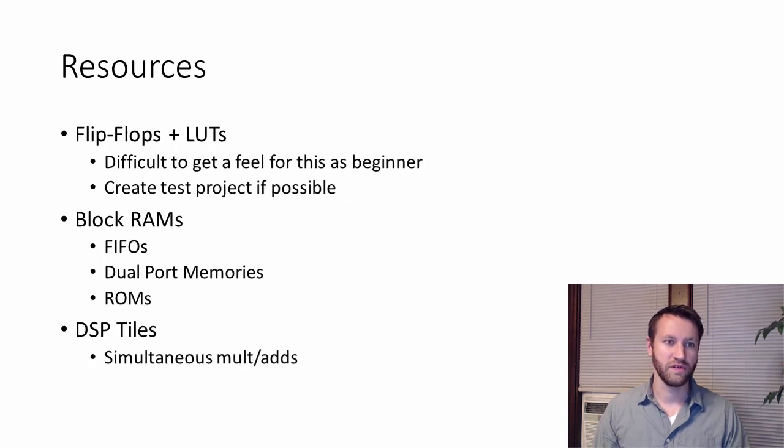Next, resources. This is the one that gets probably the most attention when people decide which FPGA development board they want to play with, for example. It's what can you do with your board? What can you do on your FPGA? How many flip-flops and lookup tables do you have access to? And this is really something that beginners struggle with, and it takes a long time to get comfortable with, oh, I think that's going to be 500 flip-flops, or I think this particular module is going to take about 1,000 registers. And that's something that you'll just get better with as time goes on.